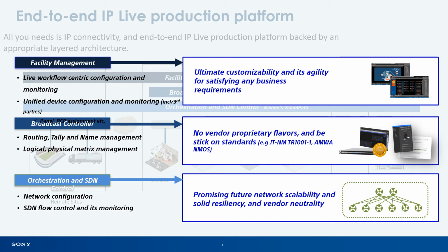But what's the mission of these layers of tools in the IP system? For network orchestration, Nevion's SDN, software-defined network, can control the flow and monitor the stream traffic, maximizing the bandwidth of the network and configuring the stream flows. The broadcast controller, simply speaking, replaces the traditional SDI router.